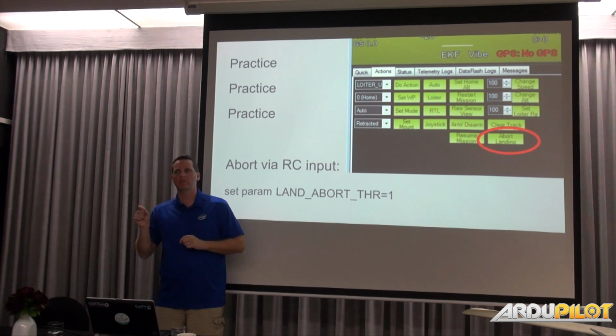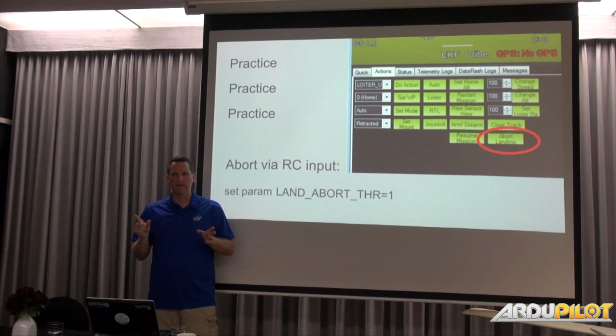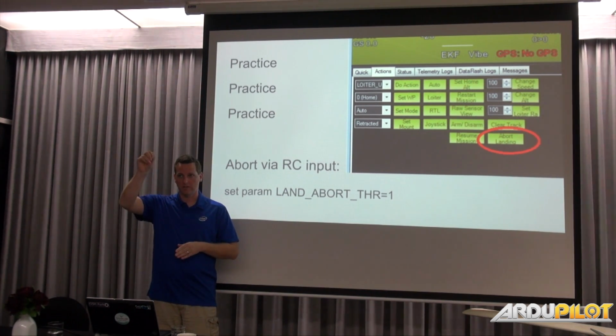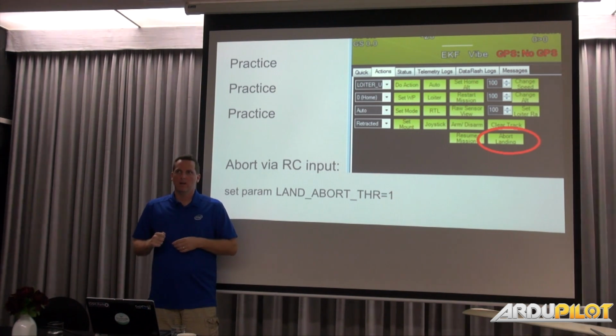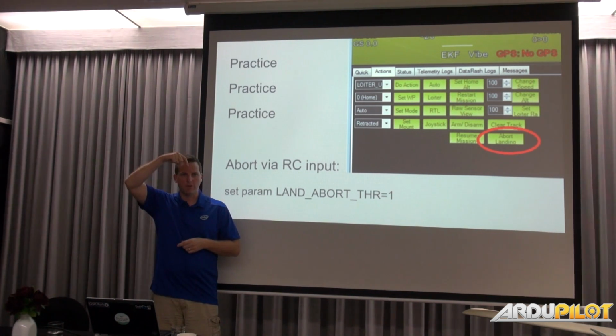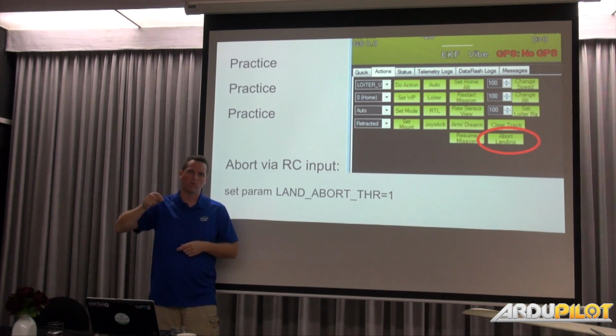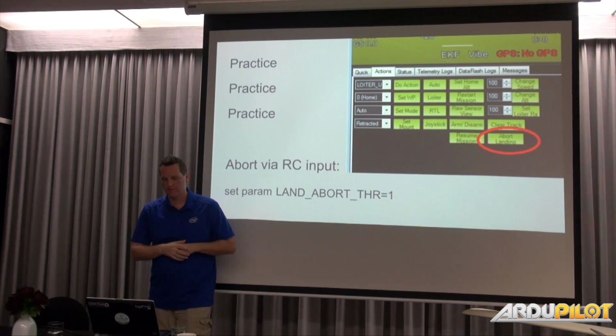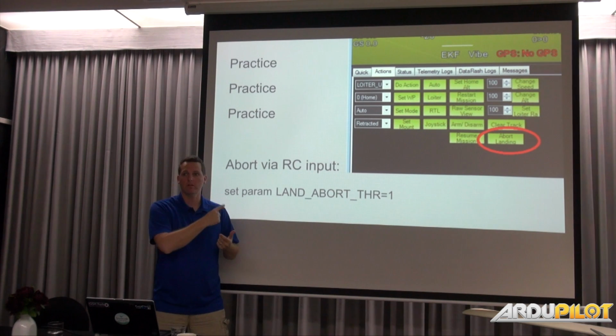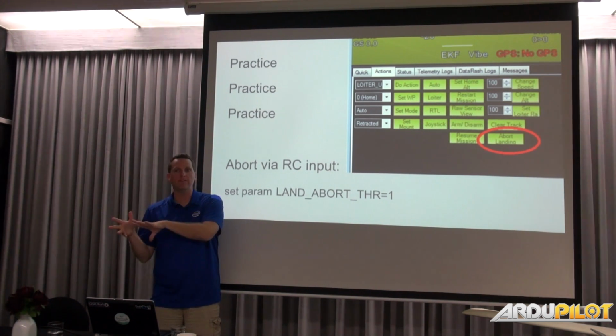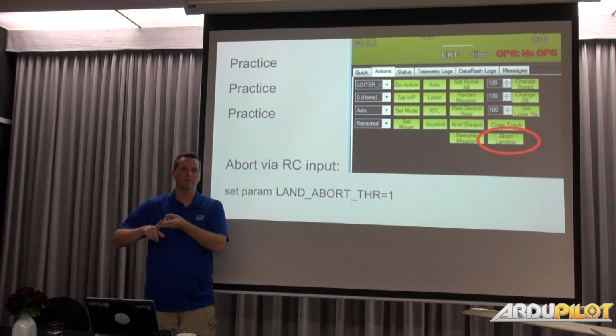If you've never triggered it, or if you didn't perform a takeoff yet, then it'll have a few conservative options, a conservative slope, or pitch, I should say. But it will just take off and then reach whatever your takeoff altitude is, or 30 meters, I think. It'll basically just hold that heading and take off, and then it will jump to either the last point you started at, the top of your slope, or it'll go to do land start, which I'll show you in a second. So if you triggered either the button here or the joystick, you get either of those 2 behaviors, the waypoint or do land start.